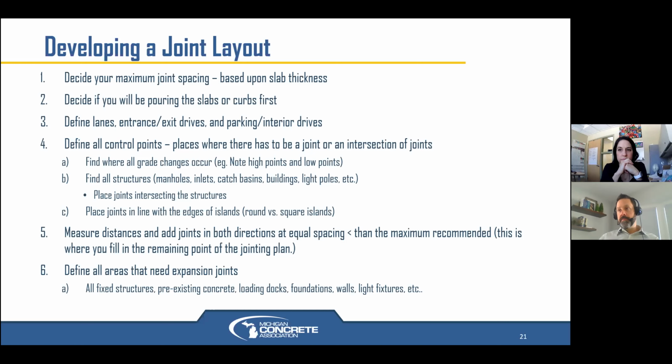And then the saw crew, hopefully, makes sure to adjust their joints to hit those structures, those castings. Some agencies like the box outs, but it's not as common in concrete to box out those either ahead of time or gap them and fill them in after, as you'd see with other states and folks around the country.